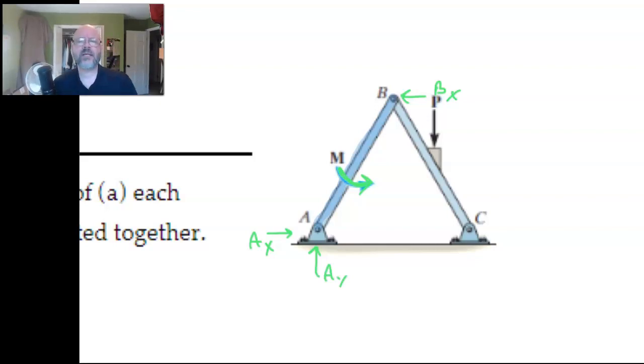So here's where you've got to think about things just a little bit, because what we did before is we just went in here and we said, oh, we're just going to have BY like this. Okay. But here's the thing. What one member does to the other, the other does back to the one, but in the opposite direction. That's Newton's third law. So if I push here, these knuckles are pushing against these knuckles. These knuckles experience a force this way. These knuckles experience a force this way. Those are equal and opposite when I'm pressing on each other.